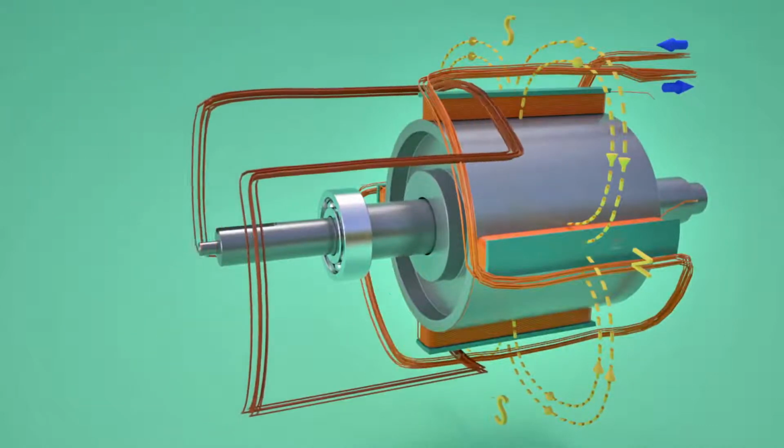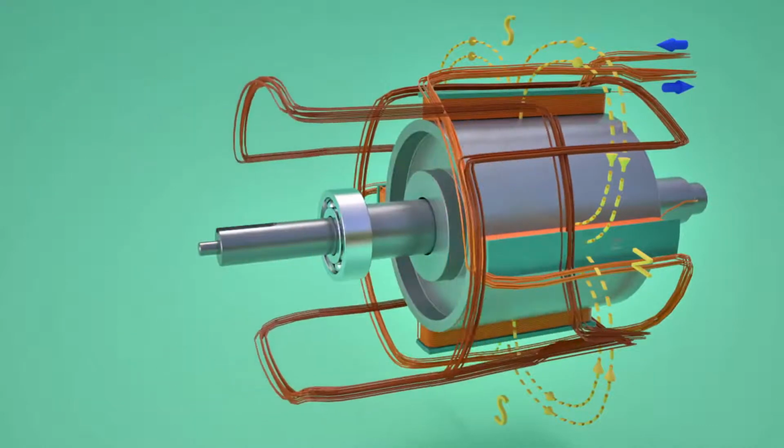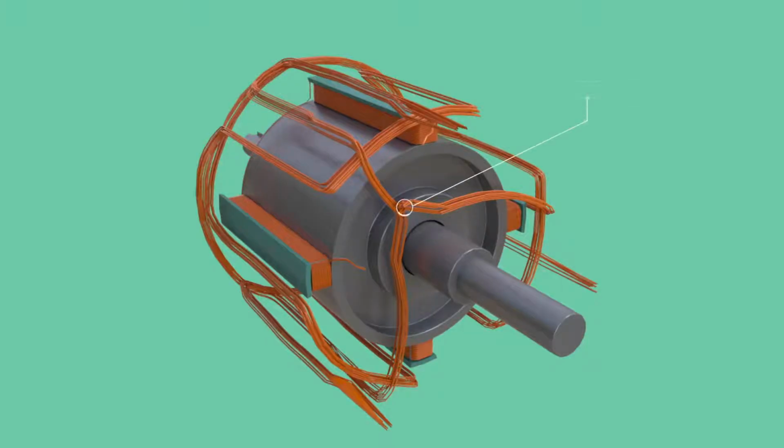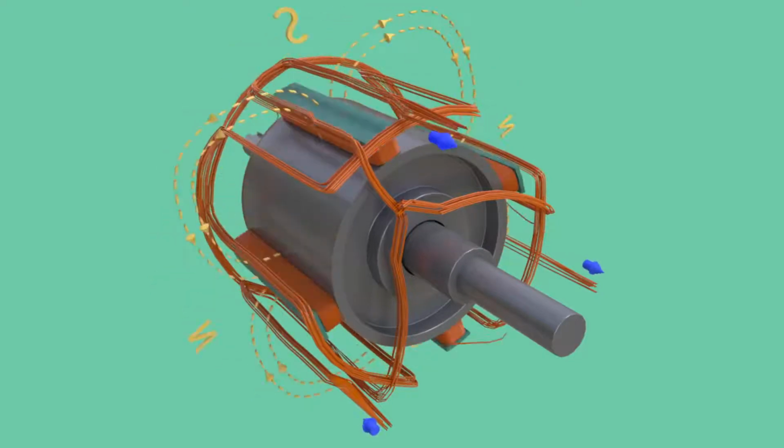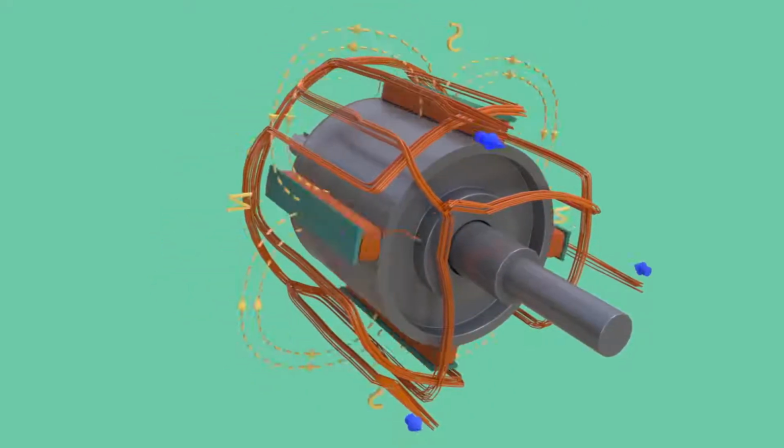For producing 3-phase A.C current, 2 more such armature coils which are in 120-degree phase difference with the first is put in the stator winding. Generally one end of these 3 coils are star connected and 3-phase electricity is drawn from the other ends. Neutral cable can be drawn from the star connected end.